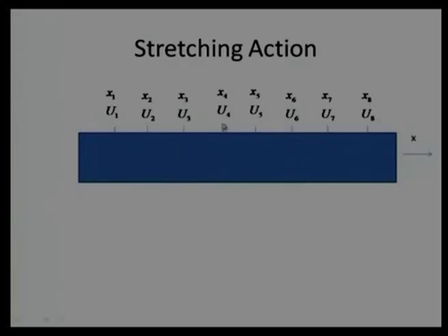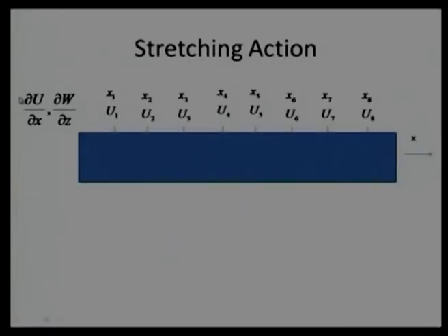What is the meaning of this? This plate is not rigid. Whatever the velocity over this surface is not the same velocity or the slightly ahead of that. It may be increasing, may be decreasing. That is a stretching term. Typical example is a rubber material which gets stretched, and we find slight variation in velocity along the surface, and that is also a source of pressure generation. So, this stretching action can be represented. However, we believe that this is in most of the cases negligible.